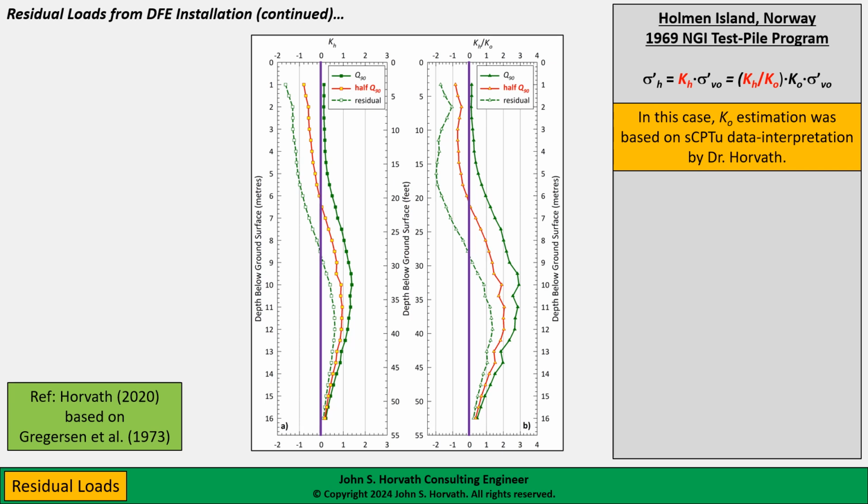I have to thank Dr. Paul Mayne, who's recently retired from Georgia Tech in the United States, for providing me with this seismic piezocone sounding and allowing me to make an independent estimate of K_0. So this is where the K_0 came from, and I highly recommend the use of either a seismic piezocone or just a piezocone to make this sort of data interpretation.